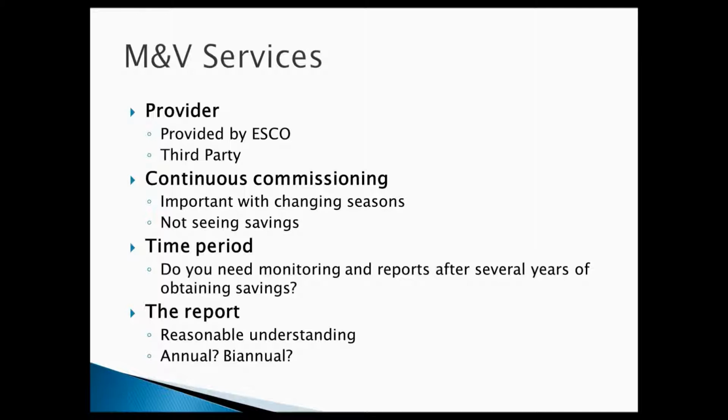Option B, retrofit isolation, is where you measure all of the parameters in isolation from the rest of the building. This is particularly common in issues like variable speed drives or things that are weather dependent, where the actual efficiency improvement that you're seeing could easily be hidden by external factors. This may be one of the more expensive and time-consuming options, but for some things this is the more accurate way to document the usage.